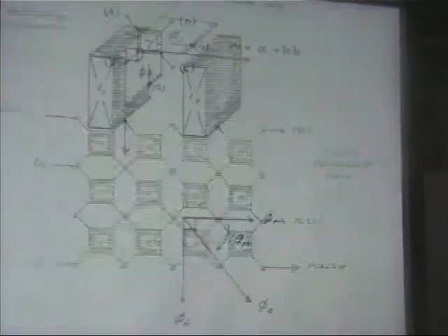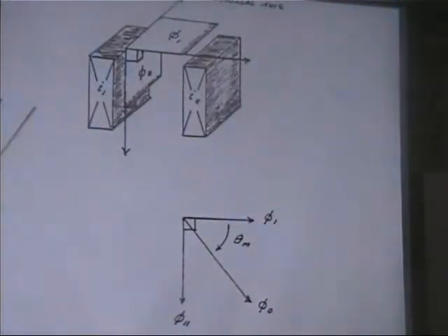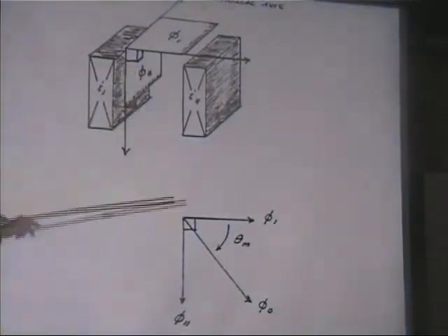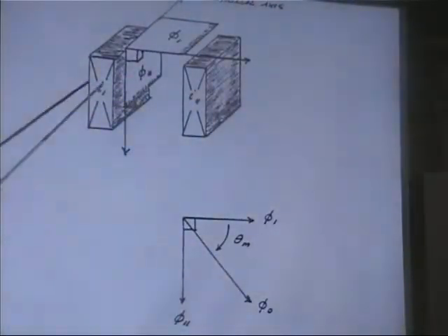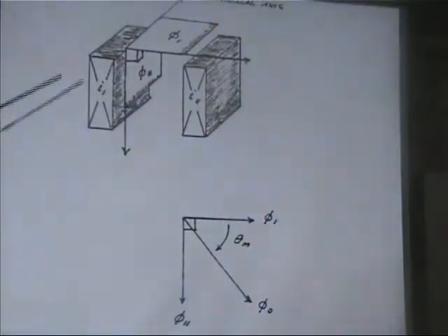Let's keep going. So basically, if we take 2 windings on the transformer, we take 2 turns. This stuff's usually wound with square material so that the space in between is not left void for leakage magnetisms and stuff to swirl around in. So basically, it's bars of copper. So we have planes here. We use the same type of mathematics that we use in alternating current. In this case, this is an electromagnetic wave.